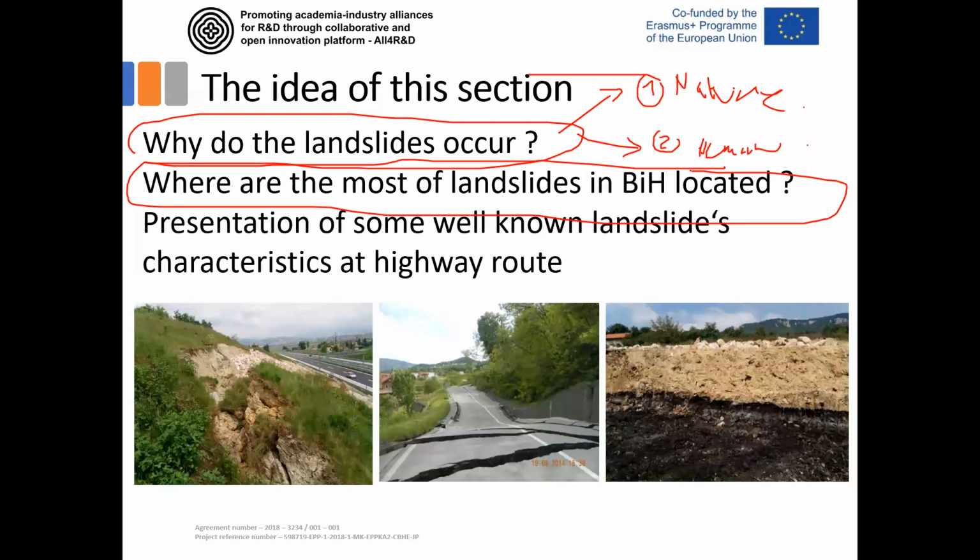They are collected in one document, one large map that gives an indication of where the landslides can be located, are located, and so on. These maps are not so detailed, but they can definitely show that in the areas where the soil-like materials are thicker, these areas are more prone to sliding.